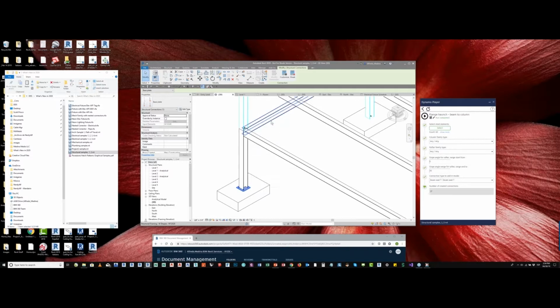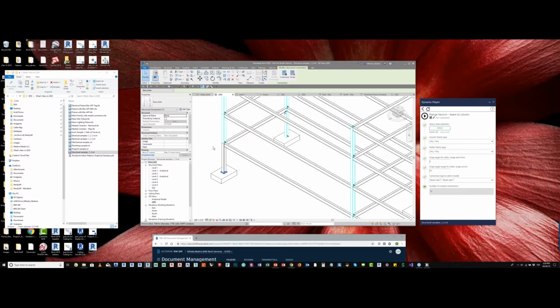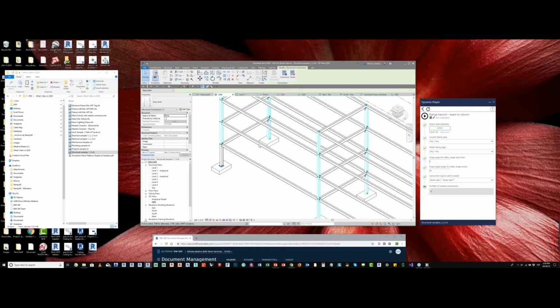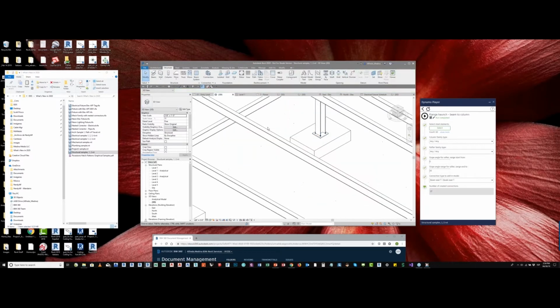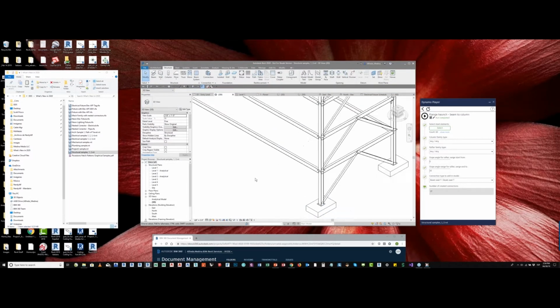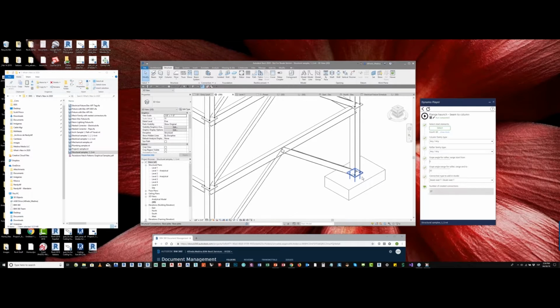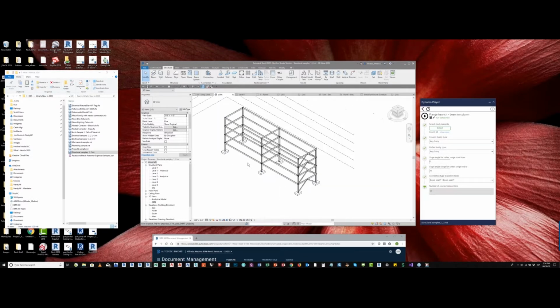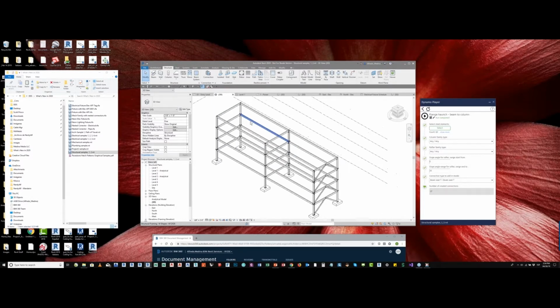So when you click on that, for all the other connections, you will see the same base plate, see? Without having to do that one by one. Now it propagates the same connection. Okay, so that's the other new feature.